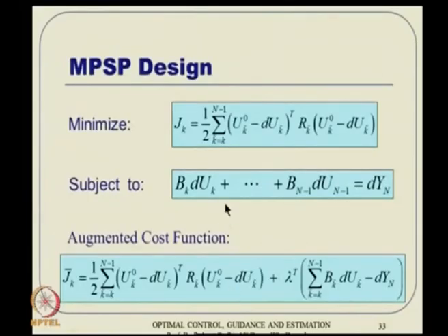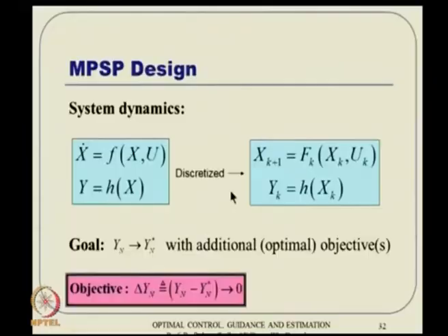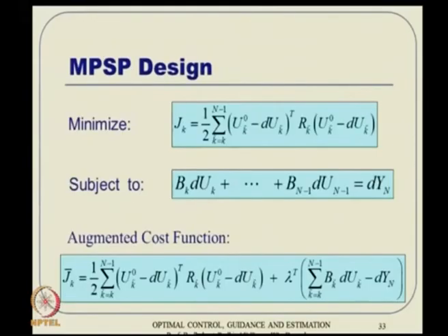Now this essentially leads us to this constraint formulation. Okay, if you start with a guess history and try to evaluate this, then to see why this comes, at every grid point I made some error in the control, and I denote that as du1, du2 and all that, those are errors over my previous guess history. Then essentially it leads to this formulation where this linear constraint comes into the picture, and if I want to minimize the quadratic cost function, I can write it that way. Okay, and it starts from Tk, Tk is my current time, and then we have the standard quadratic cost function with linear constraints. So it is possible to solve this in closed form.